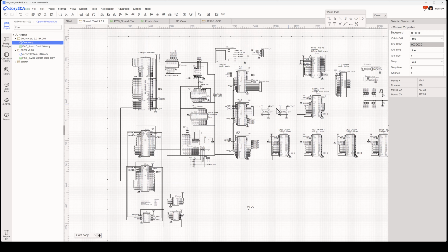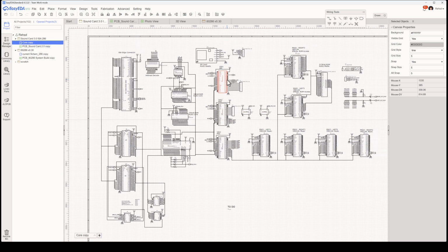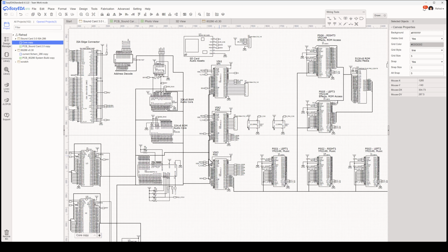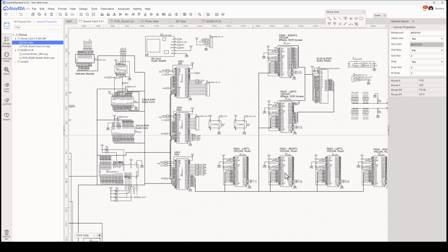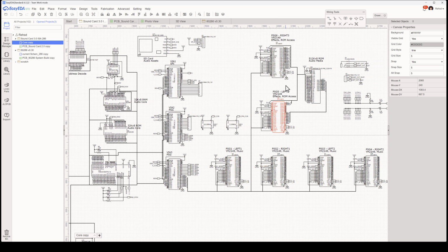And then I get up here and I have these three VIAs, and I have this VIA down here and half of this VIA. Those are managing when all of these different sound generator chips are enabled. And so each sound generator has 3 channels essentially. And so if I have 6 of these times 3, I've technically got 18 channels to work with. And this allows me to basically control those 18 channels across the 6 programmable sound generators.